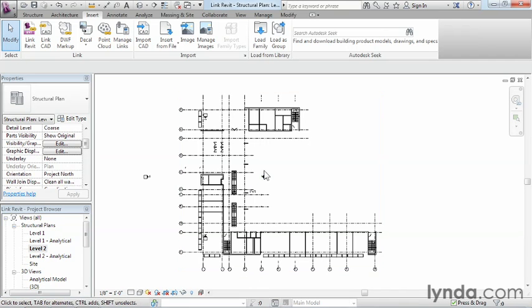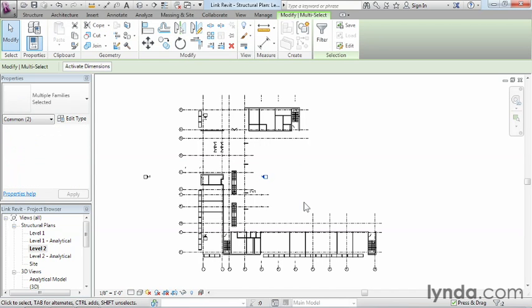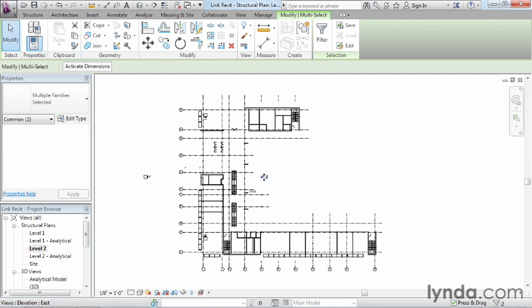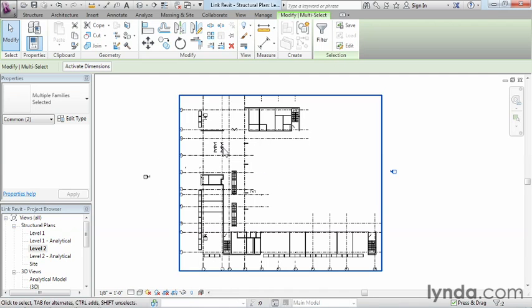We're going to look for these elevation tags. Now, the elevation tags, as long as they're sitting right there, aren't going to allow us to see the entire building if we went to the east elevation or the south elevation. And the logic behind that is the fact that it's currently sort of inside of the building. So let's just move this out so that we can see in this direction and be able to see everything